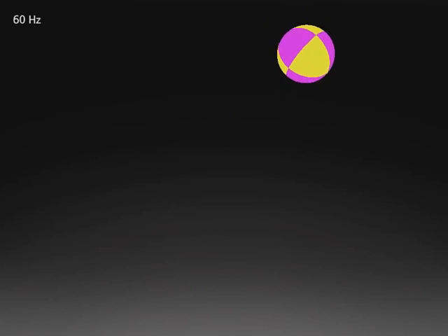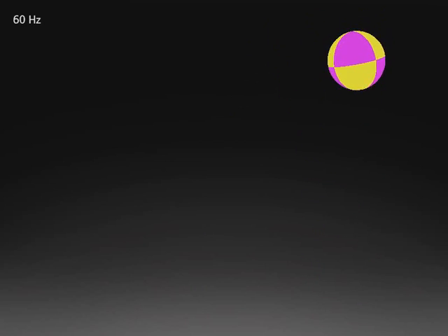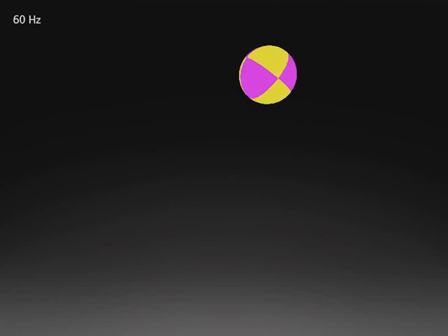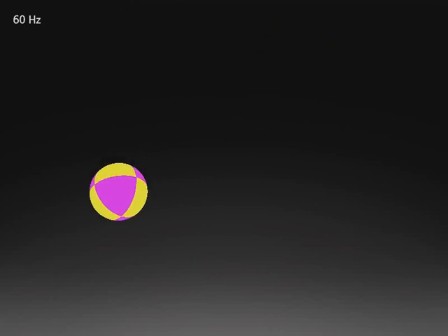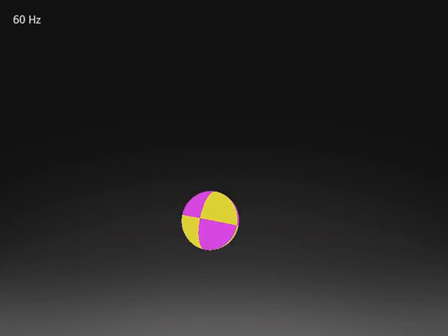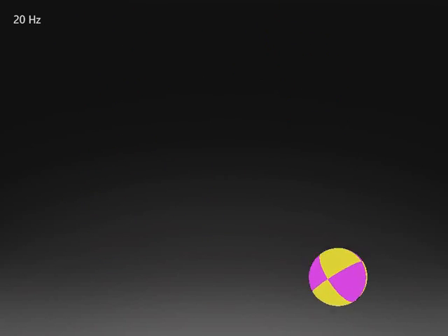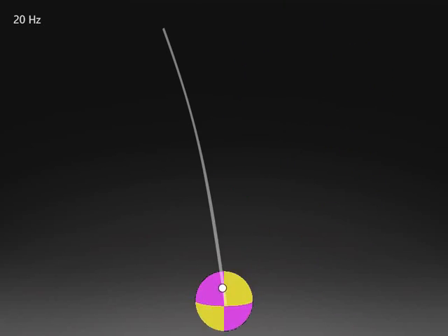The human visual system tracks objects in the real world as well as on a display using smooth pursuit eye motion. Current displays present discrete images for an extended period of time, while the eye is tracking an illusion of continuous motion. If the refresh rate becomes low, this leads to an averaging in space instead of tracking in time, called hold-type blur.